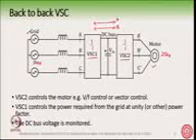So then we use this VSC1 and VSC2. What is the basic principle of operation of this? VSC2 is used exclusively for motor control, because it feeds the motor. So this is exclusively used for that purpose. So VSC2 always looks into the motor. For example, you can have vector control on the motor or you can have V by F control, and this VSC is used only for that purpose.